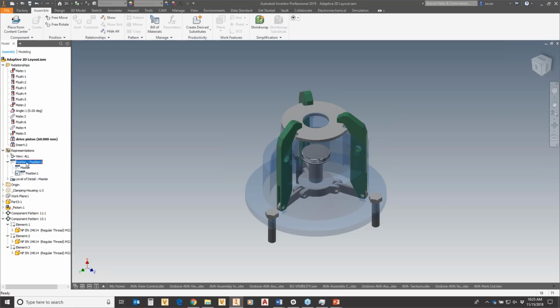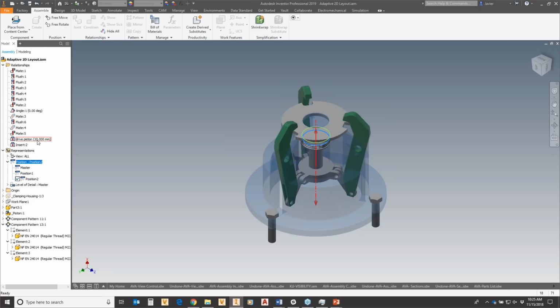I'll right-click on this again and create another one. It always starts off back to the default, and this position might be maybe a halfway point, if you will. So in this case, I'm going to go ahead and make it halfway between that. I'll make it 35. So here, I'm going to right-click on the constraint that I want to modify and override that, make it 35.